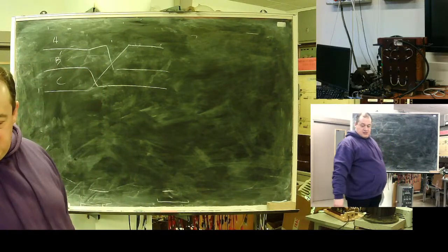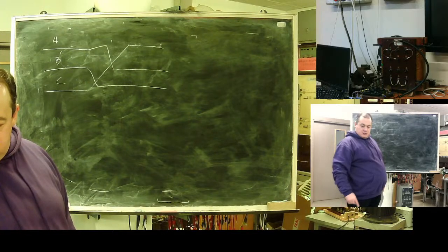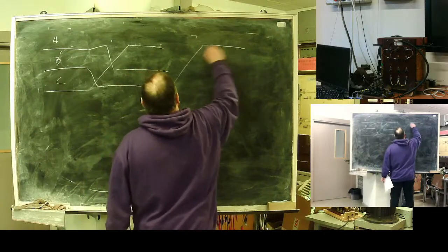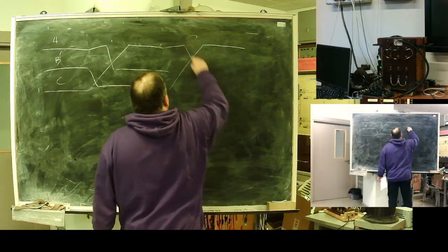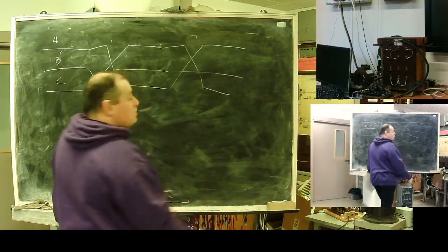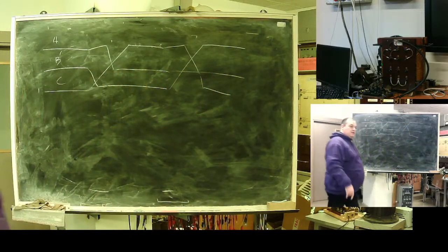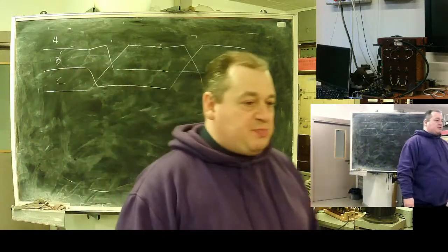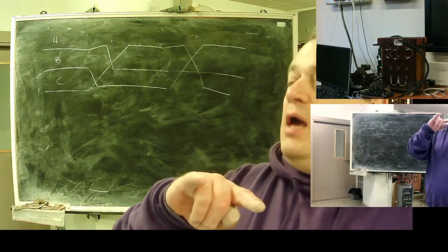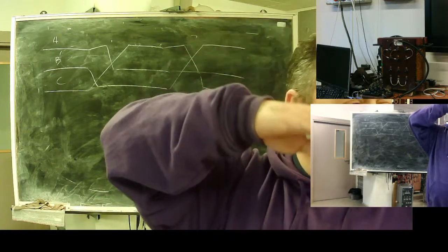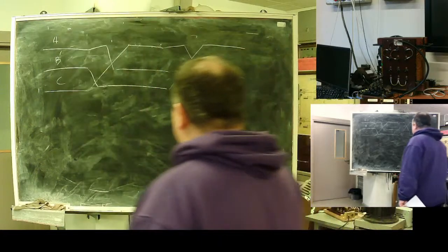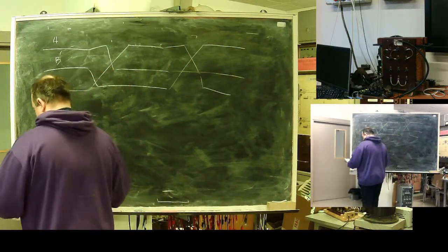What will be next? Next, B should go up. Something like this, and so on. Nice picture, transposition. The idea is to make capacitance via ground equal for the whole line. So that's the idea of transposition.